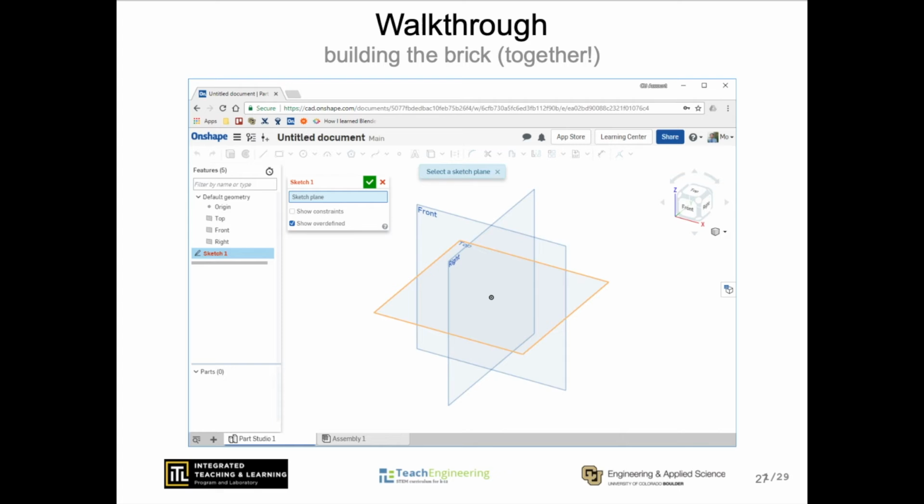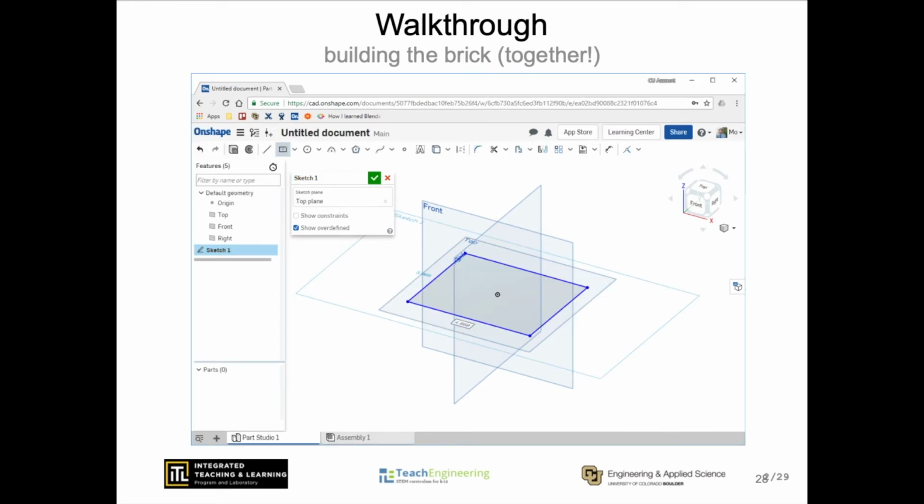When you're on the Onshape website, go ahead and log in and create a new project and go into 2D sketch mode. Start by picking a plane. It doesn't matter which plane you pick, it's arbitrary, but the most sensible choice would probably be top plane. Add a center point rectangle at the origin. You always want to model about the origin. It'll help you use symmetry later.